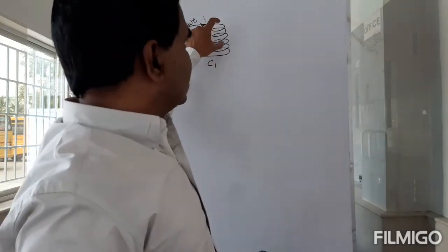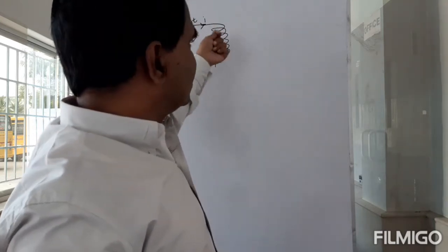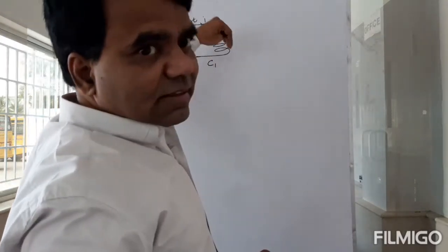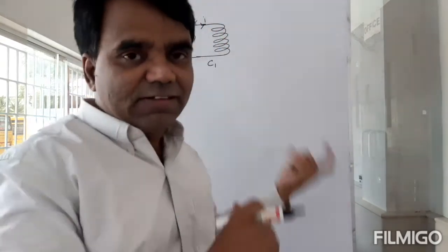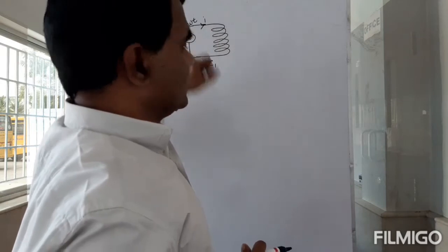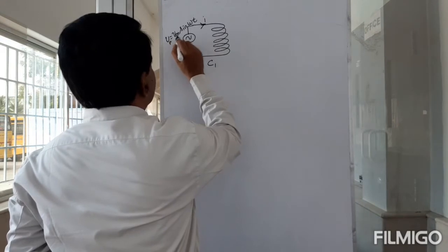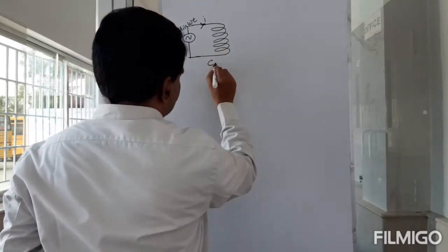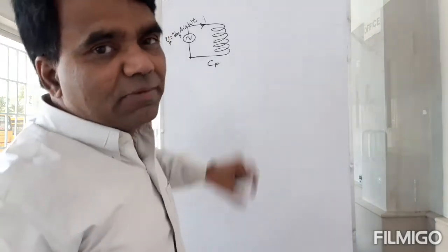And there will be a voltage, a back EMF that is getting created from this, where this current is changing. This current will produce a flux, and that flux is changing because the current is changing. Because the flux through this coil is changing, there is self-inductance, and because of the self-inductance, you have a back EMF that will oppose this. So this voltage V, I'll call this V_p, it's better. So it's V_mp sin(omega t). This coil is called the primary coil now. P stands for primary.